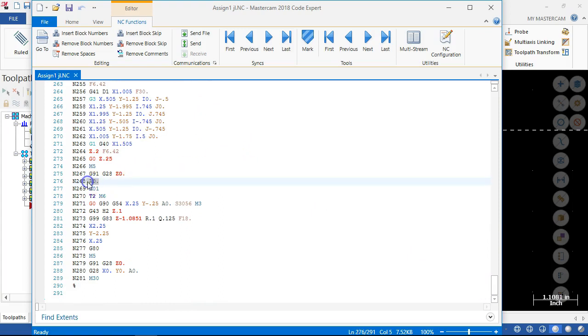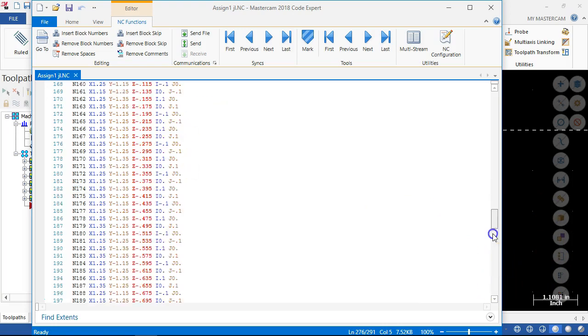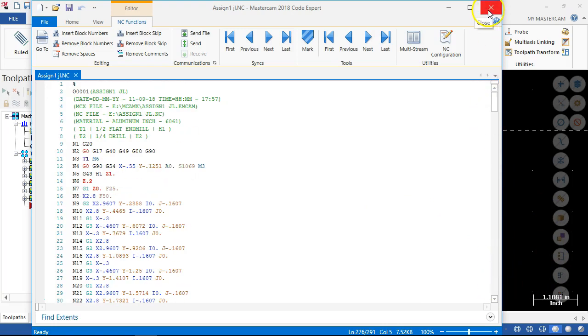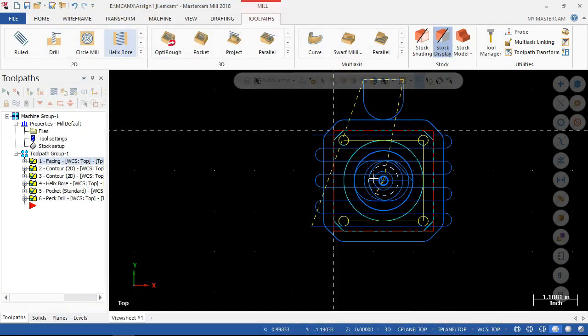The one I would watch out for that jumps out is this thinks it's got a fourth axis. Anytime you see an A and there's not an A, guaranteed that program's not gonna run. All right, so unless I have a fourth axis rotary, that A position actually does a call where we need to pick a different post processor.